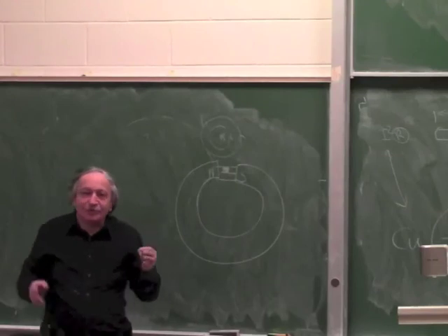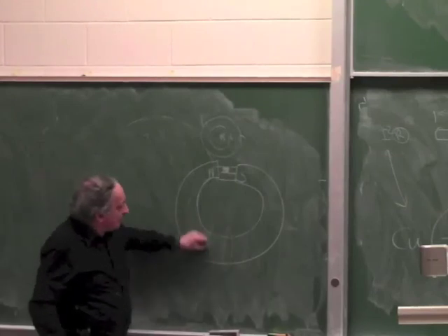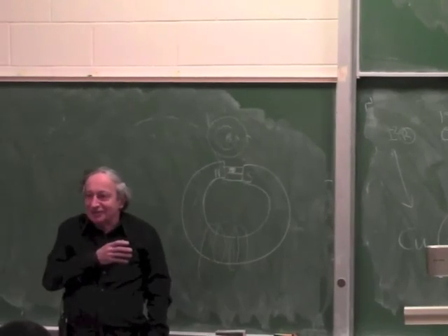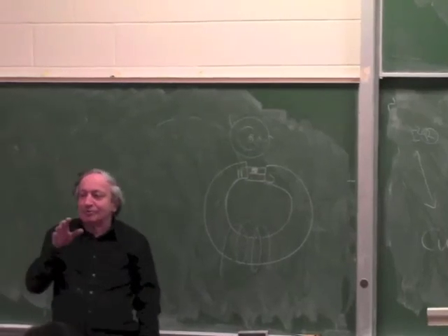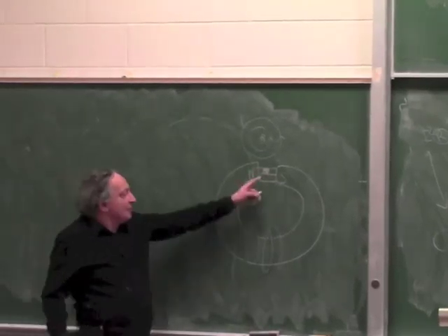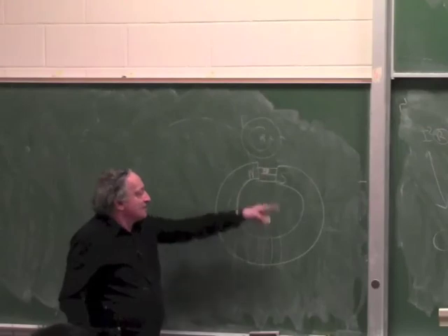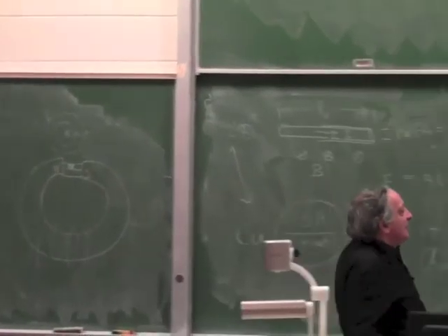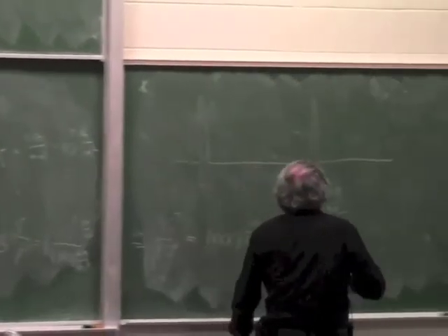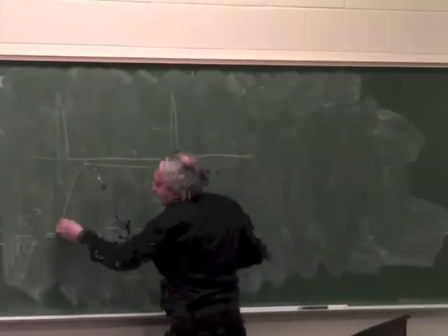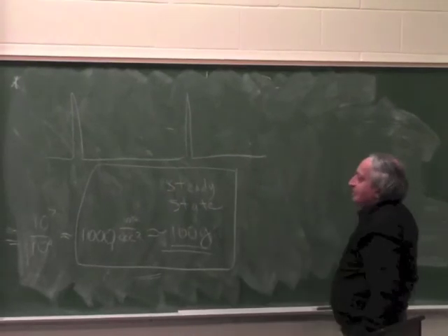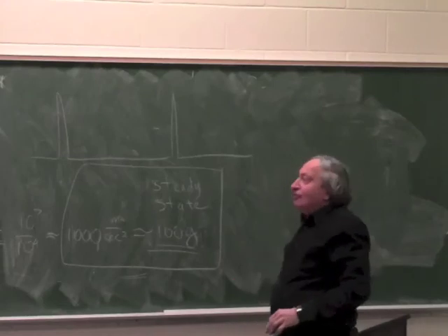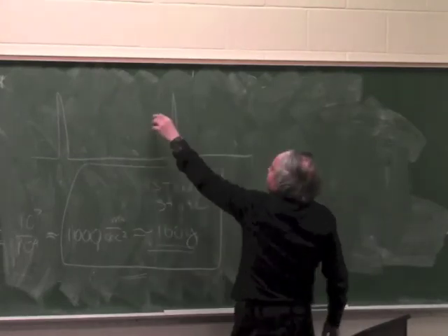So if those of you don't know it, the way you make magnets, you put a big coil around them and send a huge pulse of current. That's how it magnetizes itself. Okay? Well, I'll talk a bit more about it when we talk about moving magnet actuators. But if you put a huge current inside, it's the same as remagnetizing the magnet. So basically there is a second limit, and this is the limit for pulse mode. So for steady state, this is the approximate limit. It's easy to remember, 100 G. Okay? For pulse mode, the limit is demagnetization.